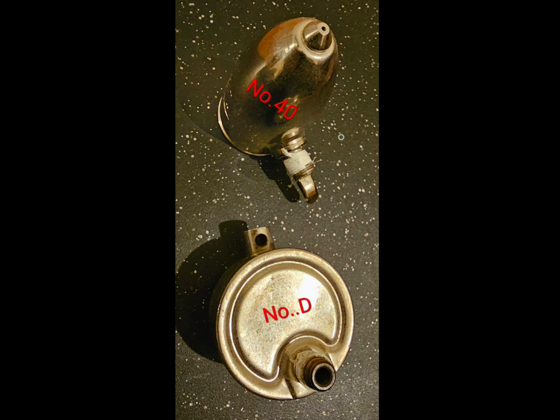Here you have a Hoffman number 40. This is one of the main vents you should be using for self-standing cast iron radiators. Why? The body of the valve itself is not too thick, meaning it doesn't hold its heat. You don't want your air vent holding its heat. You want your air vent's temperature to modulate along with the temperature of the radiator. You don't want the radiator doing something different and your air vent doing something completely different. That's how you end up with steam pressure still built up, but your radiator is cooled down, and your air vent is still nice and hot and says, hey, I don't need any heat, I'm good. So you don't want that. So the Hoffman vents are good for that.